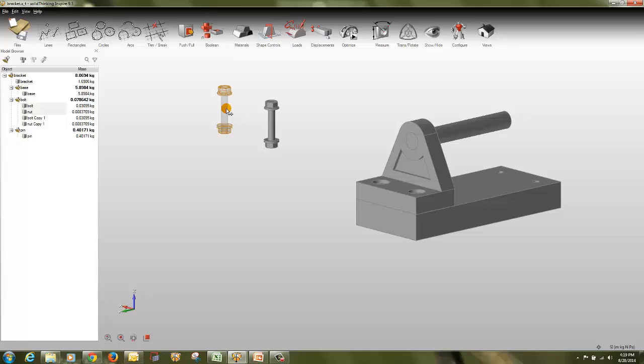The arrow with a positive sign should come, not the negative sign. Drag it to somewhere else. First leave the mouse button and then the control button. If you first release the control button and then the mouse button, it will only move, it will not copy. So you have to keep pressing the control button and first release the mouse.